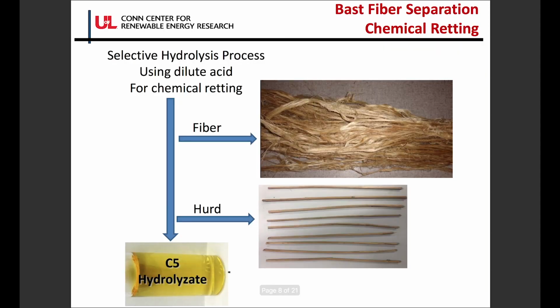The majority of the time when we are taking the fiber out, we are doing something called mechanical decortication. It's a dry process, fairly low capital intensive, and when you draw comparisons to paper making pulp, you can make mechanical pulp, newsprint pulp, which is fairly low quality, but a high yield pulp.